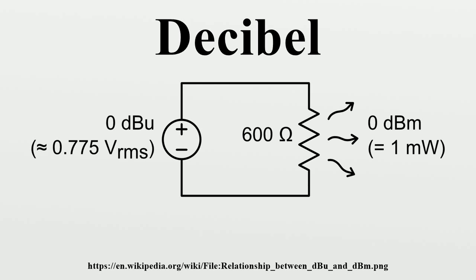History. The decibel originates from methods used to quantify signal loss in telegraph and telephone circuits. The unit for loss was originally miles of standard cable. 1 MSC corresponded to the loss of power over a 1-mile length of standard telephone cable at a frequency of 5,000 radians per second, and matched closely the smallest attenuation detectable to the average listener. The standard telephone cable implied was a cable having uniformly distributed resistance of 88 ohms per loop mile and uniformly distributed shunt capacitance of 0.054 microfarad per mile.